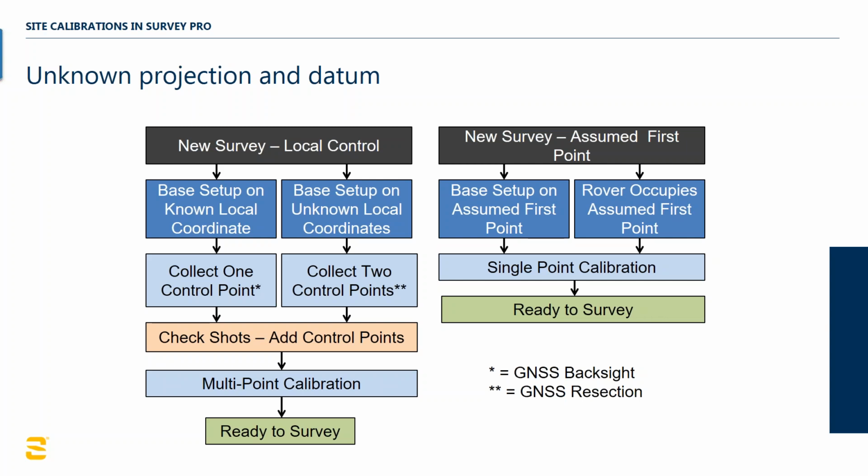Any stakeout, exactly. But if you're just doing data collection, you can put in 2 calibration points, get started, collect 1,000 points, and then add a third and a fourth calibration point. When you hit solve after that, each and every subsequent calibration point will readjust all measurements.